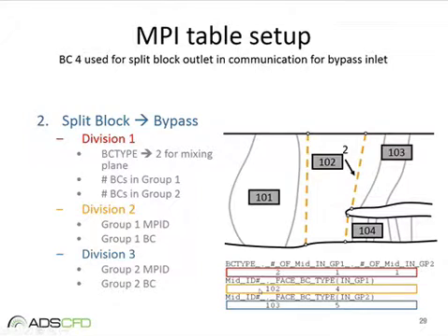Moving on to the second row, again, we're looking at the splitter side of the interface. Our MPID is 102, which corresponds to the splitter, and our CFD boundary condition is set to 4. This is a special case: for the exit condition that feeds into the bypass duct for the split flow setup, we should always set that boundary condition to 4. We wouldn't do that in a normal scenario, but only for the splitter mesh feeding into the bypass duct, we should always set that boundary condition to 4.